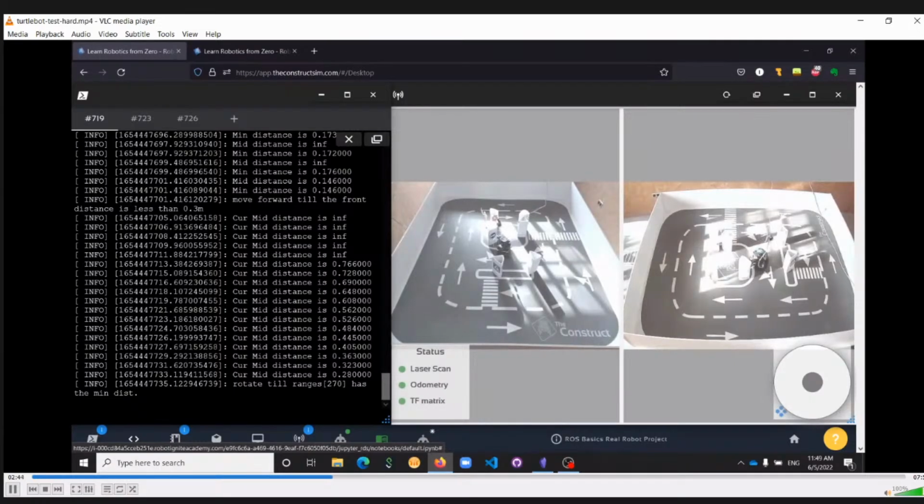My first version of this project, I also actually calculate the average distance in the range array to make sure that I'm not just using one of the elements. I'm using maybe 10 of the elements. That's another way to calculate the average distance from the robot to the obstacle at the middle. That's good.